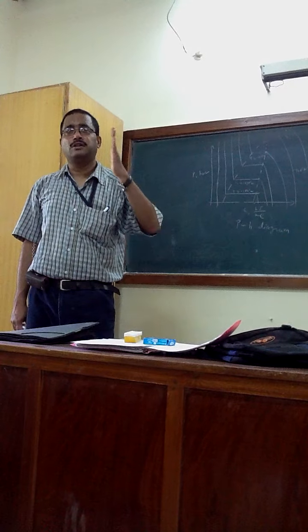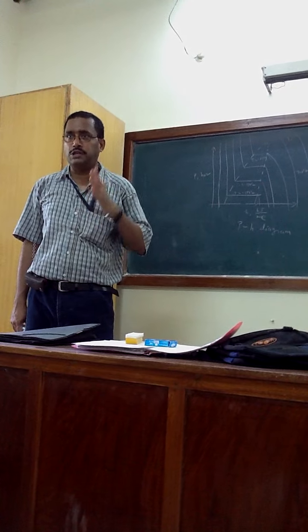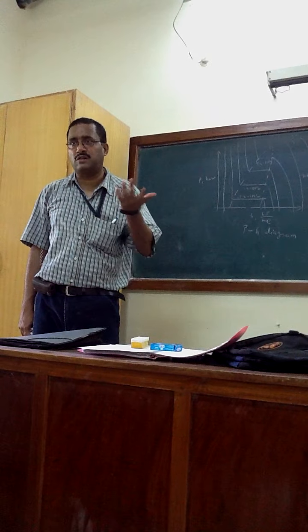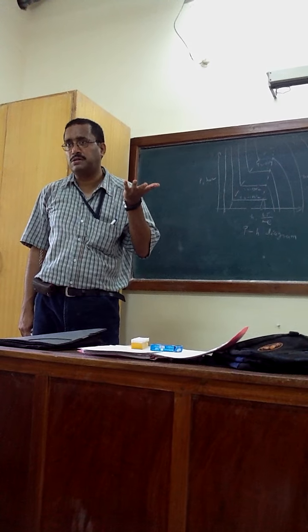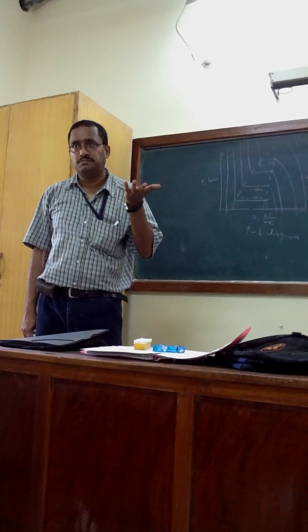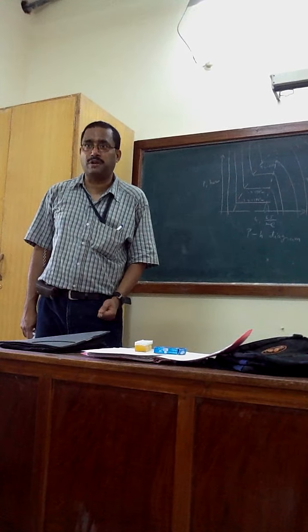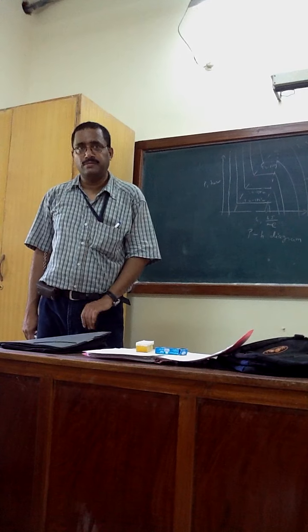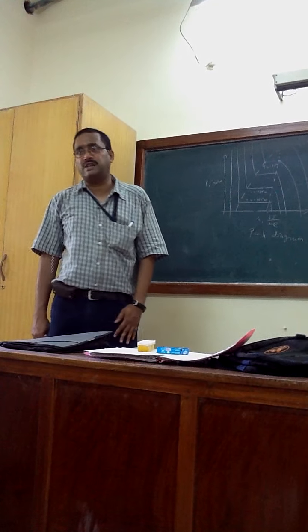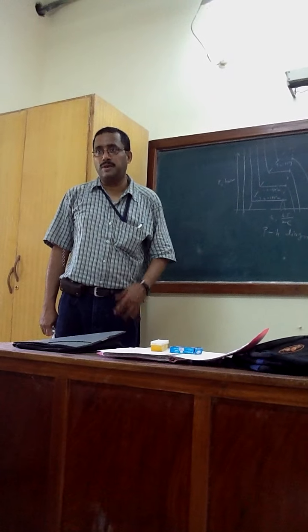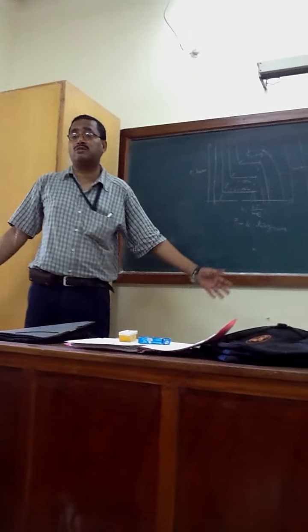The thing is that experimentalists will be there. We are all engineers. Some of our other friends will work in the lab. He is measuring pressure, volume, enthalpy, entropy at particular temperature and pressure. He will give you data. You just see that Van der Waals may not be matching perfectly with this experimental data. With experimental data SRK may not be matching properly. Peng-Robinson will be matching properly. Some data we can see Van der Waals is doing fine.